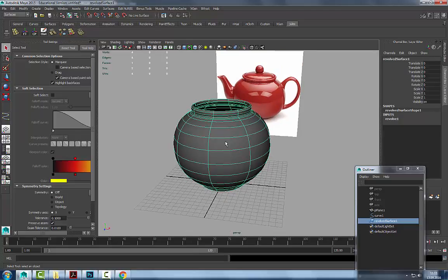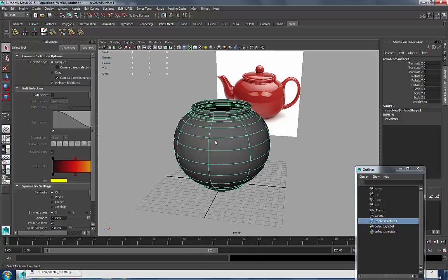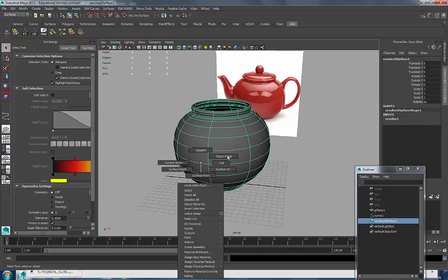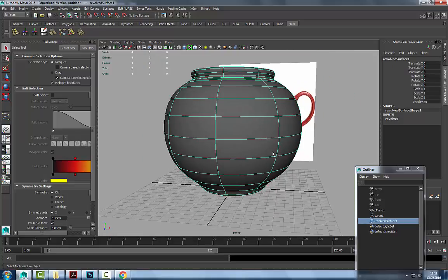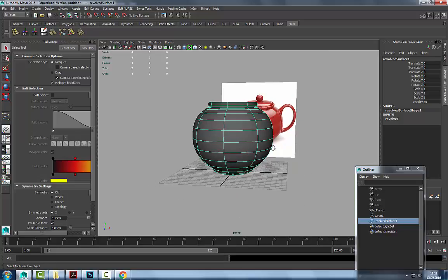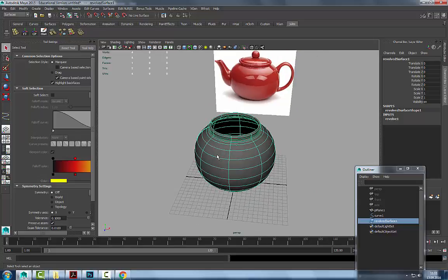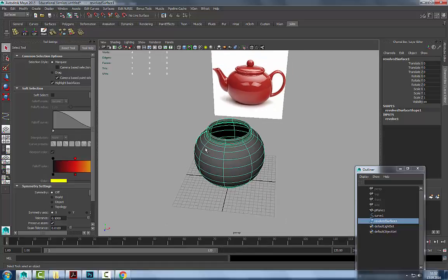So what we're looking at here is no longer a polygonal primitive. If you right click, you can see that this has different components. This is what you call a NURBS object in Maya. It's like a curved surface. We just quickly did this to arrive at this shape. So let's say, okay, fine, it's going to be a flat one. We're used to working with flat geometry that doesn't have thickness. But it's still a NURBS object, so I'm going to have to make this into a polygonal primitive.